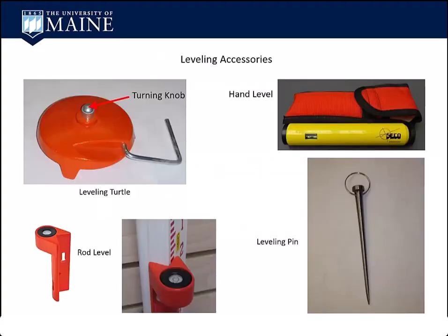These are just some accessories that go with leveling. A turtle is basically allowing you to have a nice point to turn the rod on. The rods we use have a flat bottom, and if you were going to rock the rod, you're not staying flush with the surface.